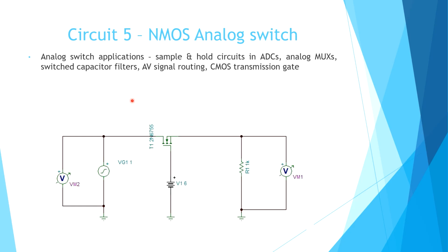the MOSFET and the capacitor will be connected, and it will be rapidly switching. The gate will be turned on and off quickly, rapidly, and that will act as a resistor here. And the equation for that is 1 by fC, where f is the frequency of the square pulse train or square waveform from the microcontroller. 1 by fC is the value of the resistance, and this MOSFET will be acting as a resistor when it is switching fast, and that will be used in some filters, low pass filters, high pass filters, like that. Okay, that's the main application there.